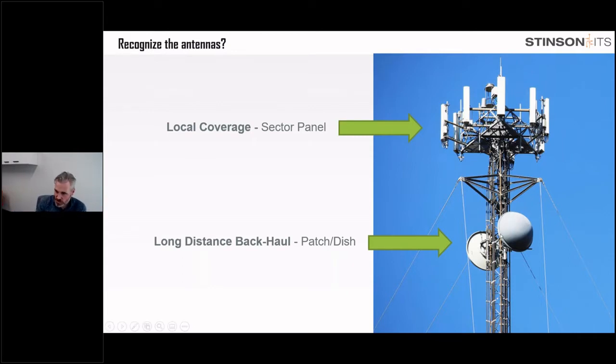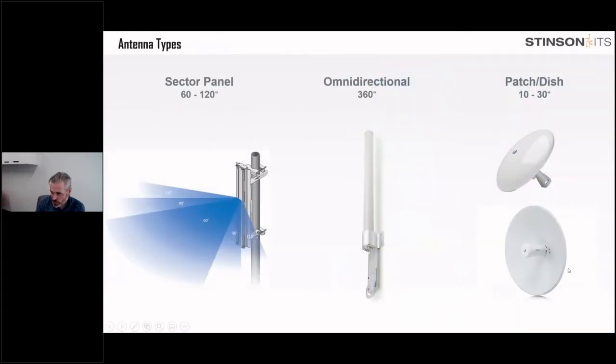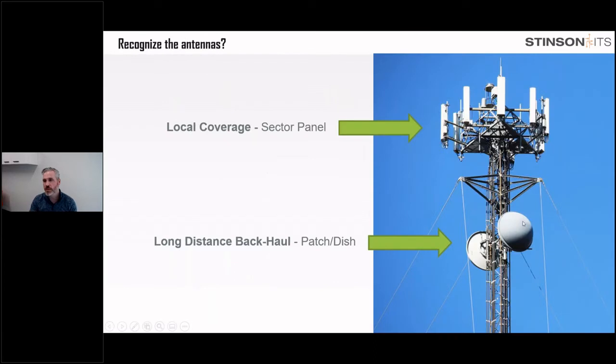And then these dish antennas, these look a little different than this previous one, but it's the same thing. They just have this cover over top called the radome that kind of stops ice and snow from collecting in there. So same thing. Sometimes you'll see a flat radome, sometimes it's a dome. But these are your backhaul connections. And so what this is likely doing is one of these is heading back to the home network, link up somewhere, it'll jump on a fiber network somewhere. And then the other radio is providing a high-speed backhaul connection to the next cell tower.